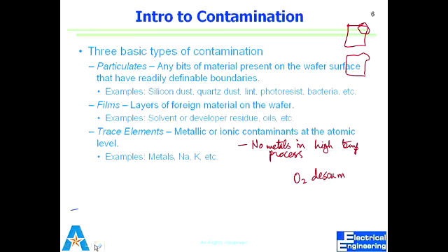So, of course, if there are metals, we cannot heat the substrate chip wafer up to high temperature because that's going to melt it. So melting is a very important topic. If a metal melts in a high temperature process, it's not just going to degrade the substrate, the electrical properties of the material. It's going to contaminate the container also. It's going to contaminate the chamber of the process.